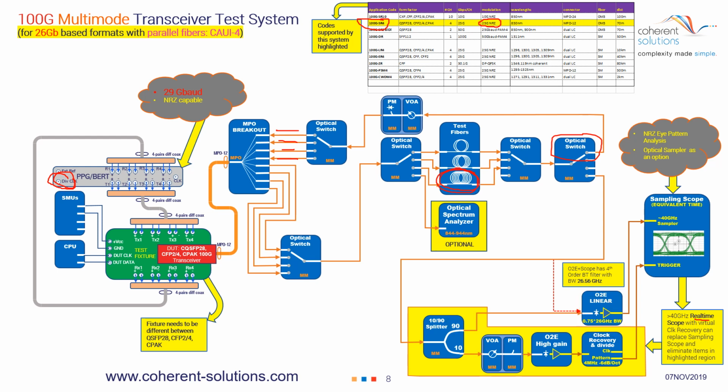In modern oscilloscopes, this filtering can be done all in digital signal processing if you have the right frame trigger and you actually know what pattern you are generating here. I'll talk more about that later. It's not required for non-return to zero signals. It is required for PAM4. We'll get to that later when we get down to our PAM4 signals, which are shown in some of these other standards, especially for 400 gig.